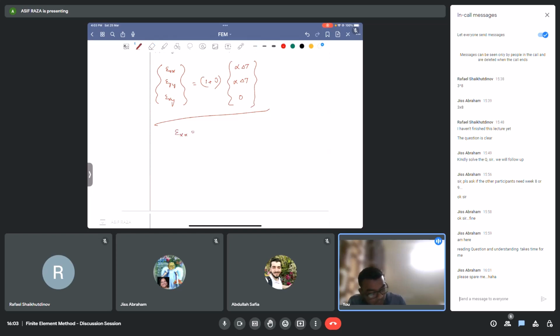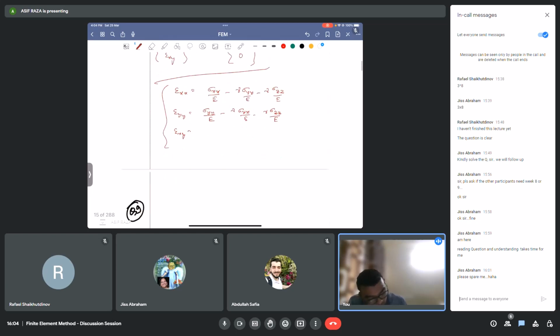Epsilon xx is sigma xx upon E minus nu sigma yy upon E minus nu sigma zz upon E. Epsilon yy is sigma yy upon E minus nu sigma xx upon E minus nu sigma zz upon E, and likewise for epsilon xy.